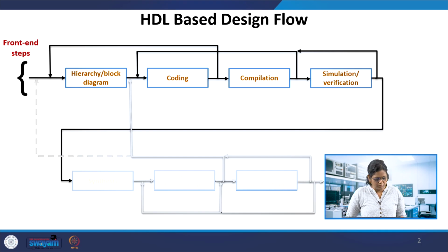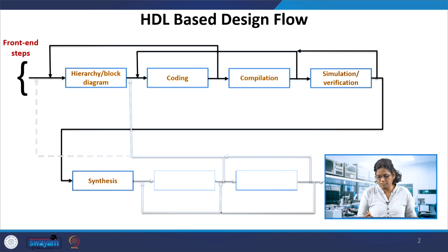And then we come to the synthesis part. After learning the designs in the combinational and sequential logics and the simulation of them, we come to the synthesis part to target this code in the FPGAs. So the synthesis finds the hardware counterpart of the Verilog code, what the digital circuit and the module has been saying.